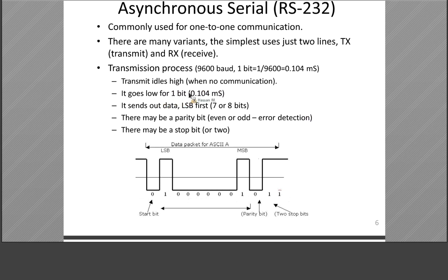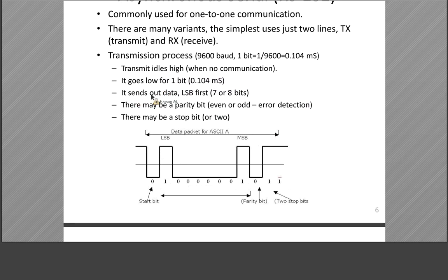It goes low for 1 bit, which means a start bit. Then it sends out data, LSB first, from 5 bits to 9 bits.